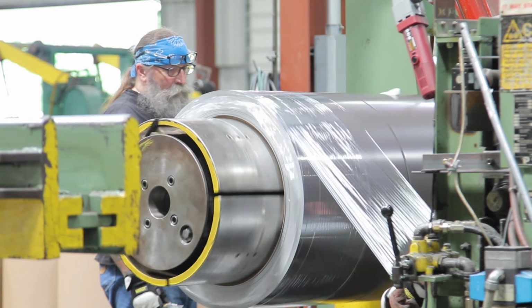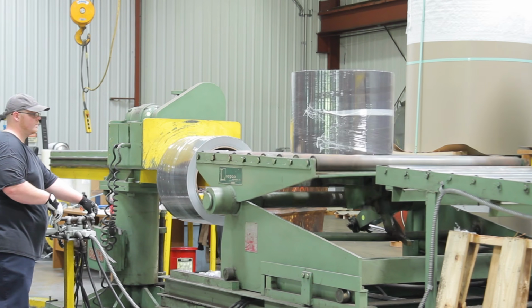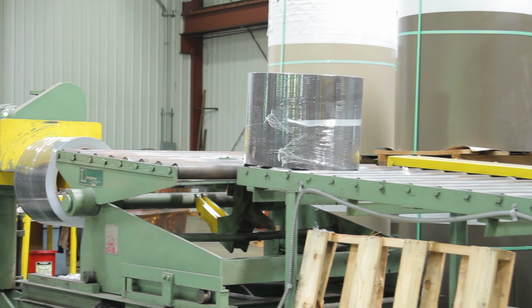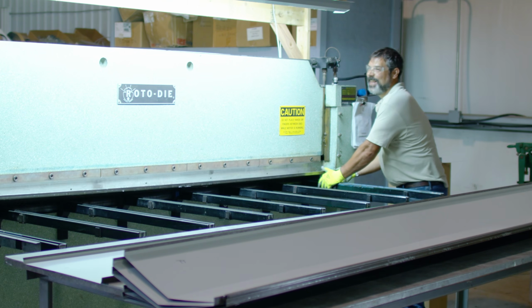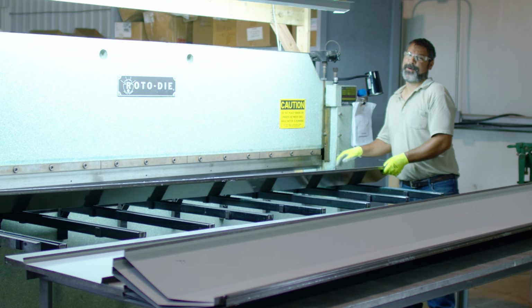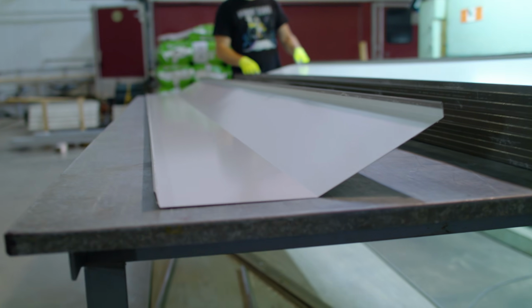Metal materials for roofing are manufactured into coils and sheets, which are then bent into the final panels and trim to be installed on a building. The most common metal material for roofing is steel, which is measured by gauge. The higher the number, the thinner the material. For example, exposed fastener metal roofing often uses 29 gauge steel, while standing seam metal roofing typically uses thicker material, 26 gauge or 24 gauge.